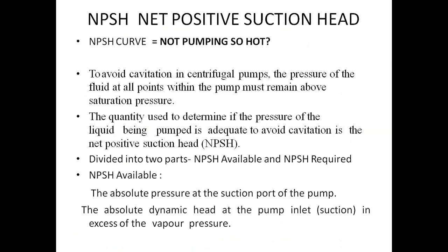NPSH, net positive suction head. To avoid cavitation in a centrifugal pump, the pressure of the fluid at all points within the pump must remain above saturation pressure.